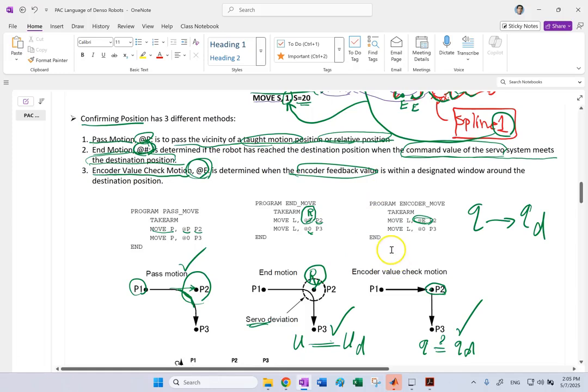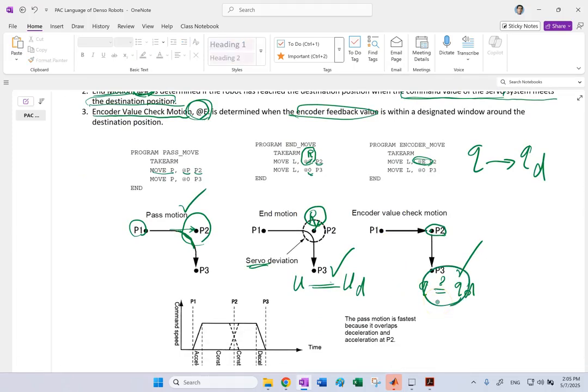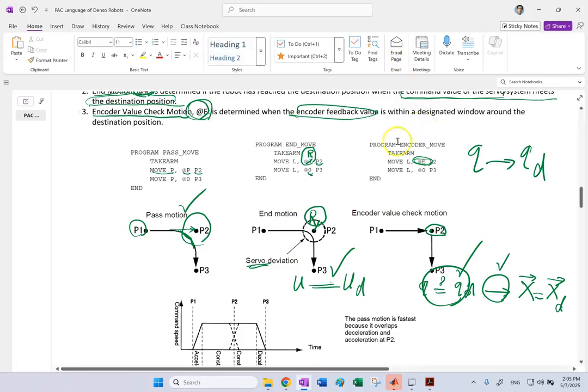So you can assume that your robot is very rigid and there is not too much gear backlash or anything. If your q equals q desired, this tells you that x, the pose of the robot or end effector, is also x desired. This only happens if the robot is very rigid and there is not too much gear backlash. Then you can say, yes, my robot is very repeatable and it can really fulfill the command.